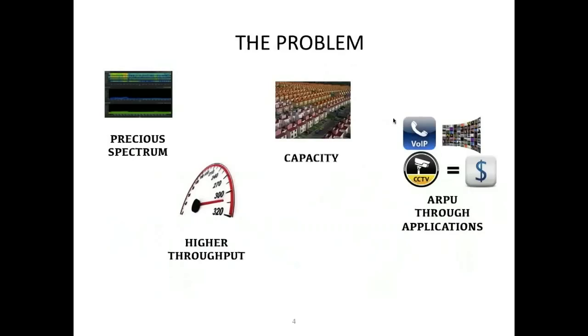Let me get into a little bit of the ePMP product line, but specifically let's start by talking about some of the problems that we think wireless service providers or other businesses using unlicensed broadband face. I have some images and some phrases here. I'm going to touch on them a little bit, but first and foremost, we talk a lot about precious spectrum. This has to do with the fact that we are operating in unlicensed 5 gigahertz primarily, or 2.4, in which case the spectrum is very key, and being able to manage interference and reusing channels that you find free is a key aspect.